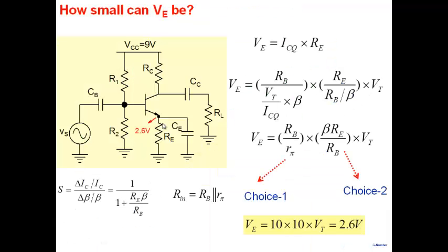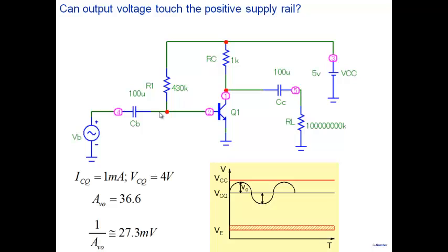Okay. The picture that I painted about voltage swing is a little bit simple here. Now let me illustrate why it is simple. All right. And I'll illustrate it with a little bit of simulation results here. So let's look at this amplifier. It's a simplified amplifier here. There's no RE. Okay. No RE here. It is biased from the base side in this particular manner here. Okay. So in this case, note that a 5 volt battery is there. RC is 1K. We have 430, and we are applying signal from here, and then looking at the output here.